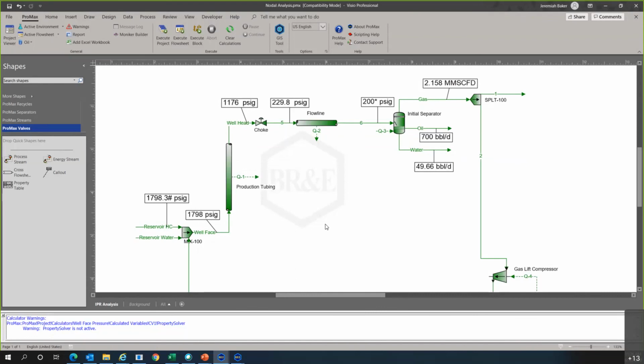You can get to some intermediate pressure, and it would just affect the efficiency of the tubing as well. So that's a great question, Bevan. We can actually add different mix points, vary the pressure there to say, okay, maybe we can mix this midway through, still get the flow regimes we want, and drastically reduce the compressor power that we need. So that's another great question that we could use the model to either prove or disprove.